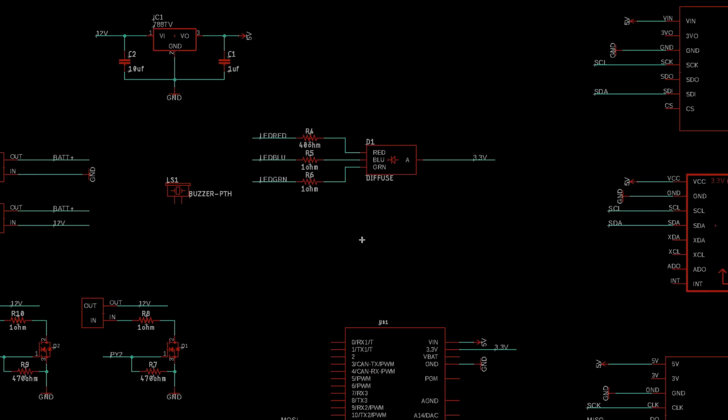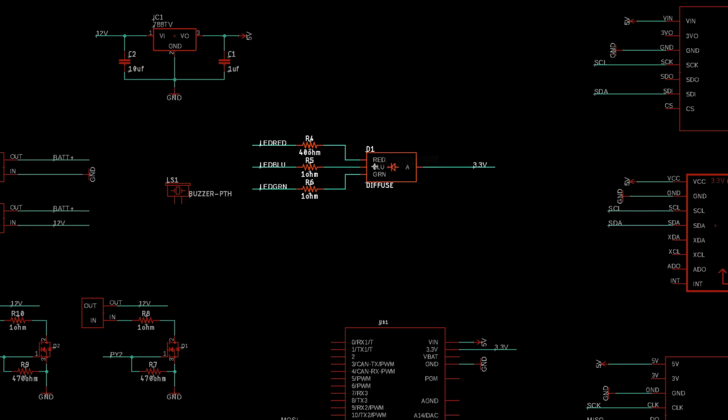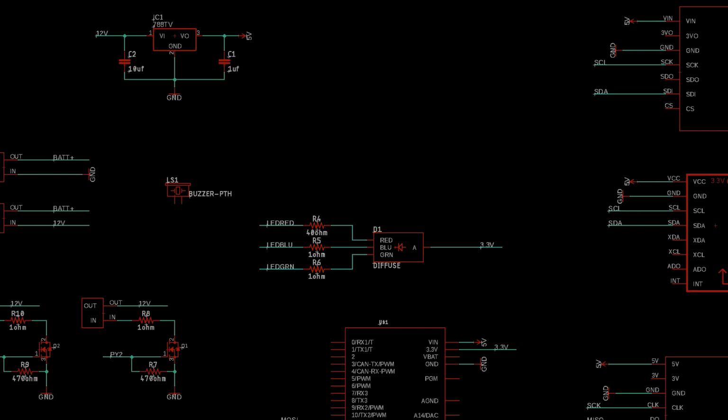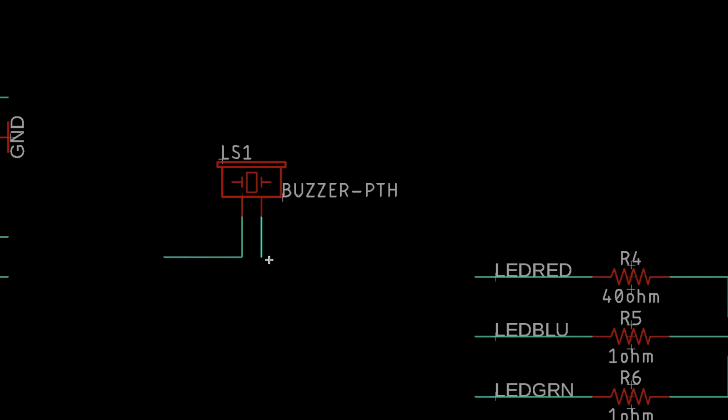How about the buzzer? Okay, so let's move this around a little bit. I'm going to move this buzzer up here. I'm going to move the LED down a little bit too. We're just kind of trying to make this look really nice. So we'll move group, and that's going down there. Okay, so for this buzzer, we're just going to draw 2 leads out of this. We've got 1 and 2. And one of these is going to be the input, one of these is going to be ground. And actually, as I think about it now, we should have only drawn 1 lead.